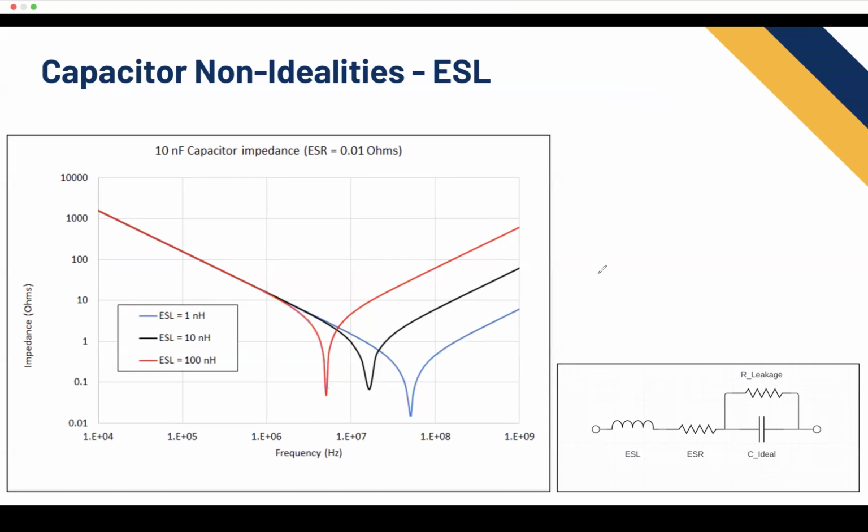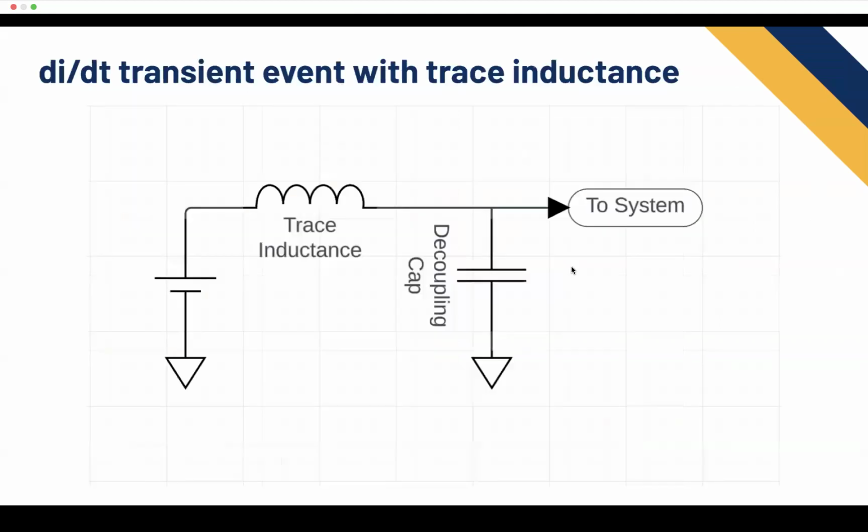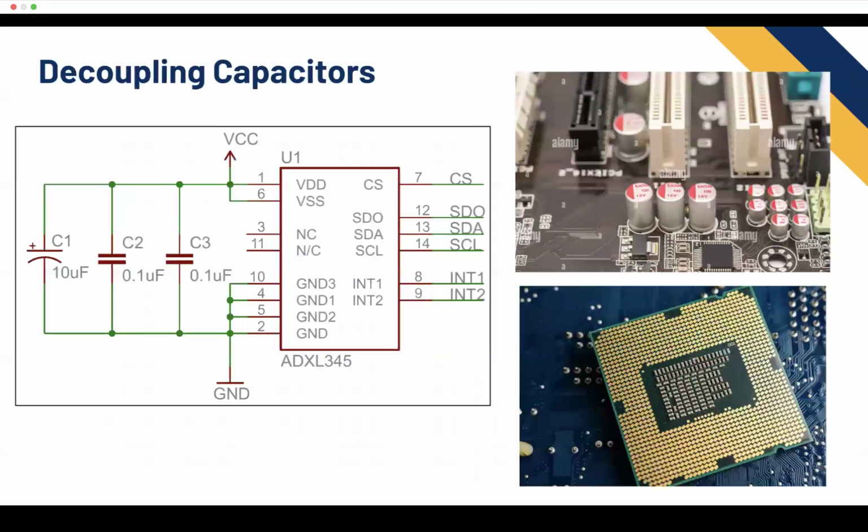And basically what that does for us is, if I can go back, usually you put like 10 microfarads, 0.1 microfarads, and then like 100 nanofarads, I think, or maybe something a bit larger than that.